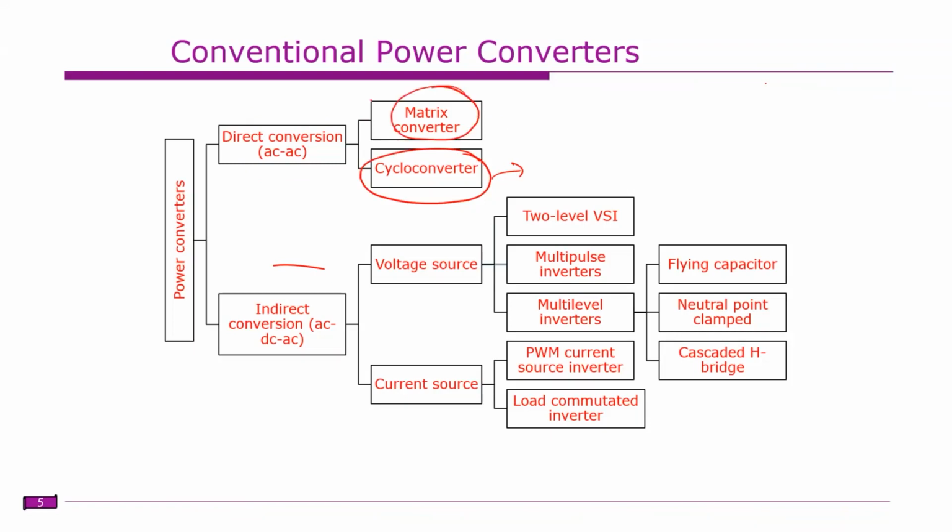Matrix converters have good advantages, but the failure rate is exceptionally high because the short circuit of two phase legs is very common in matrix converters. We have to take all these necessary precautions when using this converter, and moreover, the matrix converter also requires a huge number of switches.